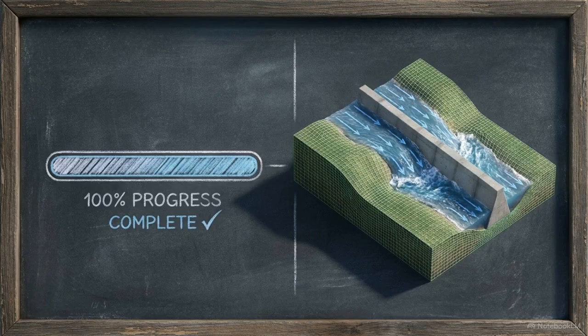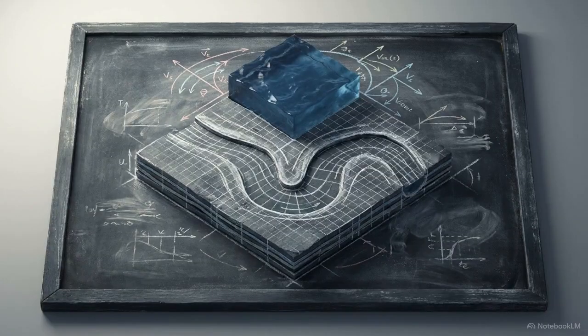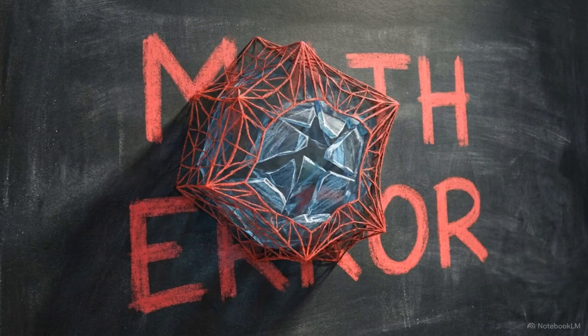Subgrid bathymetry and break lines are strict engineering workarounds. They allow solvers to cheat computational limits without sacrificing physical accuracy. With the boundaries, the mesh, and the friction set, the unsteady flow simulation begins, pushing the hydrograph's water volume through the mesh over time. The greatest threat during this phase is model instability, a condition where the underlying math breaks down and the simulation crashes.